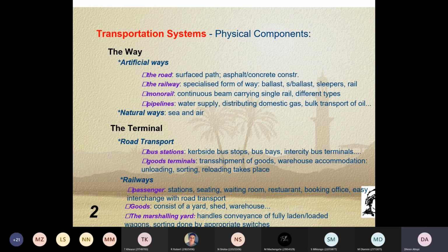So by the time these stresses reach the subgrade layer, it's much lower than the carrying capacity of the subgrade. Right? You must have heard the terminology CBR, California Bearing Ratio, that determines these stresses that I'm referring to. So as long as the stresses that are imposed on your selected subgrade layer are lower than your subbase,